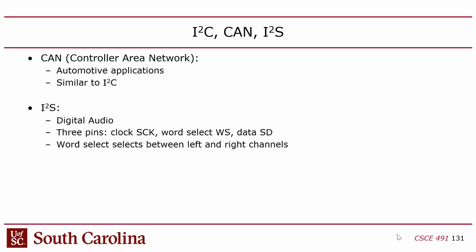So it's a little bit different than I2C, but the packet format is very similar. It uses a very similar transaction format to I2C. It's a little bit more complicated, though. It has a CRC, a cyclic redundancy check error detection code, unlike the simple acknowledgement mechanism that I2C has. So the packet format is longer. It starts to look a little bit more like USB. In fact, CAN is almost like a mixture between I2C and USB in a way.